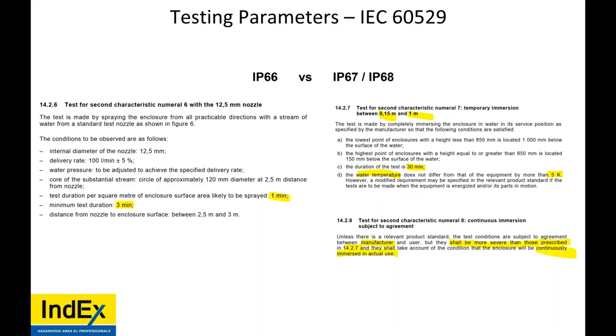But to give you an idea, humidity, which is the gaseous, vaporous form of water, and hot air rise. If you have a breather drain at the bottom of the device, it's really only operating as a drain. It is a very poor breather because that humidity is going to stay trapped inside and rise to the top of the box. And when the box cools down, that is going to condense into water. That water vapor is going to turn into a liquid. So why are you going to keep finding water inside your boxes? Because you don't have a breather near the top side of your box.